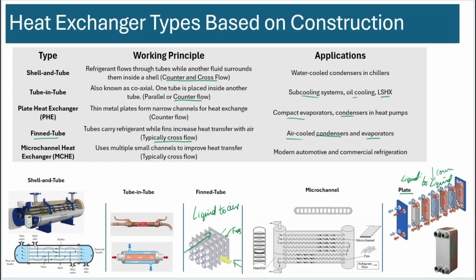In the microchannel case, you have fins. You see the zigzag patterns? These are fins. And then the channels are inside the gray colored section here. If you take a cross section of this, if you cut it and look from the side, you will see there are several small channels. These are where the refrigerant flows.